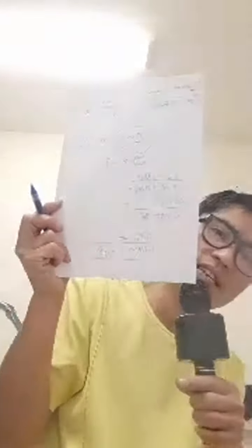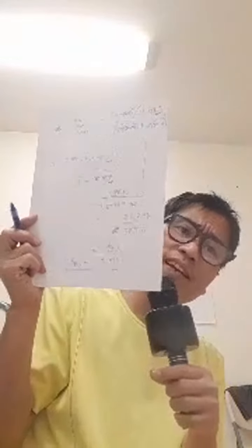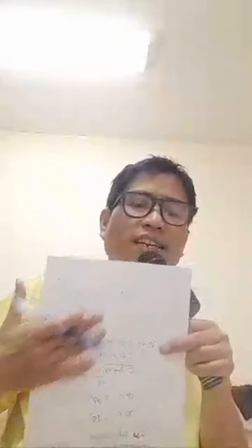We should go back to our overall material balance, or the component material balance, because we now have the mass fraction of benzene. The main purpose of computing this, guys, is that the problem gave mole percent, not mass percent. So to be consistent, use the mass percent. So F times Z is 1744, equal to D times the distillate composition 0.9415, plus the W, the bottom product, which we don't have yet, times xW.